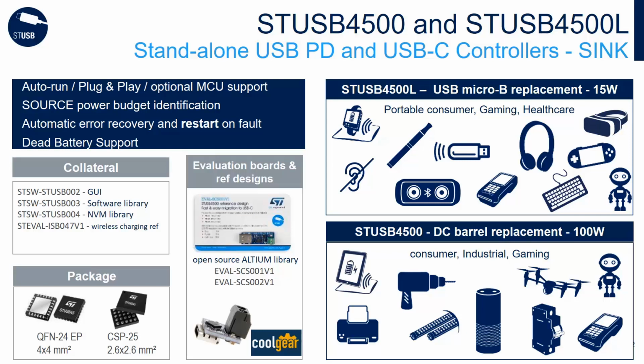and based on the capabilities defined by the PDO profiles, it will negotiate with the source side device to establish a power contract. Although the NVRAM on the ST USB 4500 includes default PDO programming, it can be customized to support any application with only basic know-how about the standard and limited software skills. No need to be an expert at all thanks to the NVRAM programming GUI that ST provides. In addition, we provide example design materials, including schematic, BOM, and open source Altium libraries for layout.